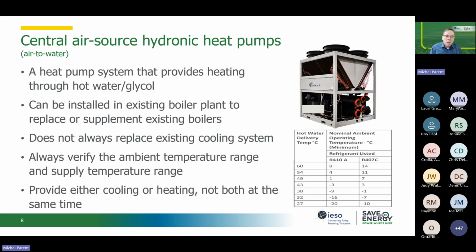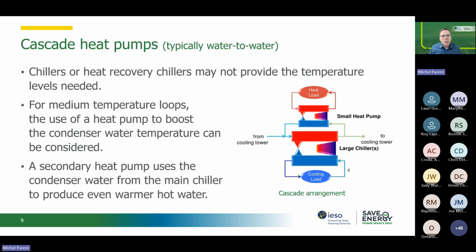It is air source. Therefore, just like the one we saw before, you need to know how much capacity it's going to lose with outdoor temperature getting colder and what's going to happen to its COP, because that is something that needs to be considered when you will program how your supplemental heat will work on your BAS, and again, needs to be integrated into your BAS.